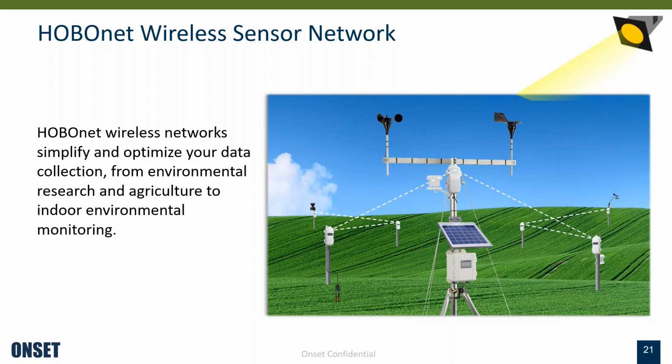What you're seeing on the posts and the lines as they're hopping from one to the other, sensors can hop up to 2,000 feet line of sight. I'll suggest where you're placing your main station could be like in the center of a Conestoga wagon wheel, and place your sensors around it. They will hop to each other. You can do 5 hops from one sensor to another. If you have a hill or an obstacle or a building to get around, you could add a repeater. Repeaters are less expensive than a sensor, maybe as much as $100.